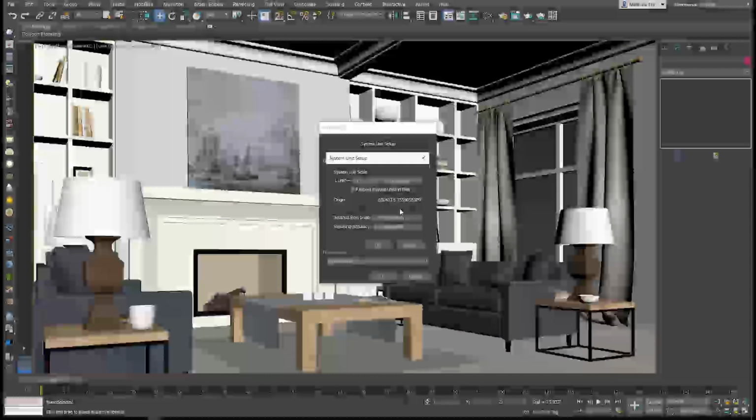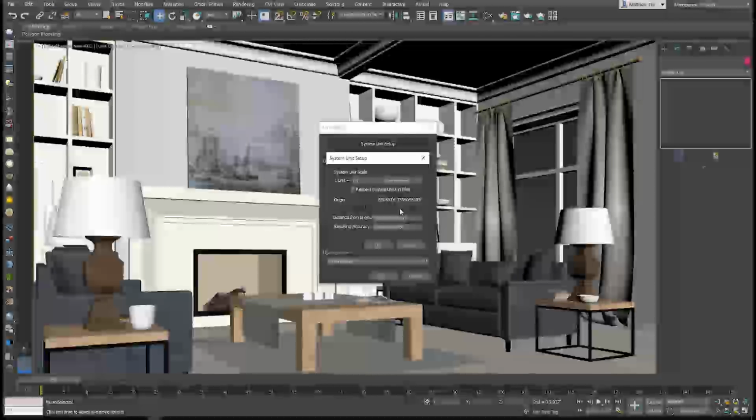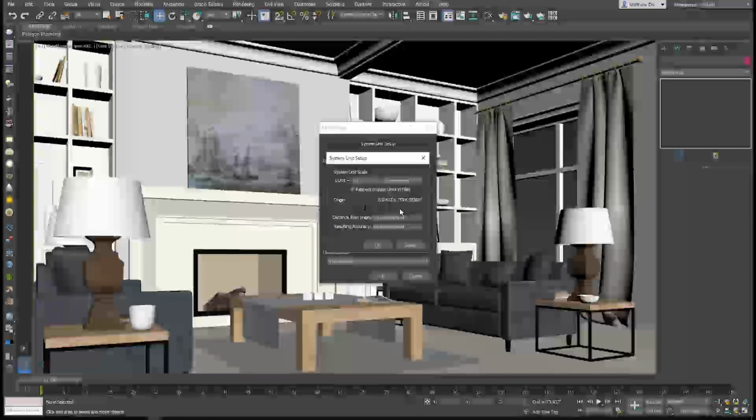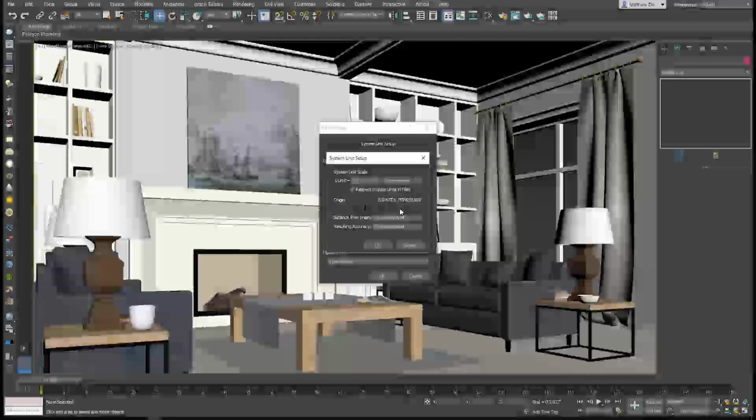Now, a few things to keep in mind when working with very large scenes. In this case, we have kind of a medium-sized interior architectural scene, but sometimes you might be working with an entire building, maybe a high-rise, an apartment structure, or even an entire city block or more. When you're working with those really large scenes, bear in mind that the further an object in your scene is from the origin of the world, that is 0, 0, 0, there are more chances for rounding errors in the math that is needed to display those objects accurately and without any kind of graphical glitches in Unreal.